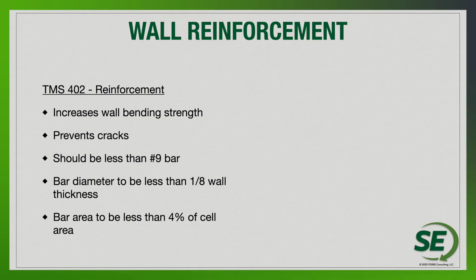We have reinforcement bar sizes that should be number 9 bars or less within the strength design provisions. And just from a practical perspective, using anything larger than a number 9 might be pretty difficult to construct, so we know that a number 9 is a good practical limit, as well as what is in the code and what has been tested.